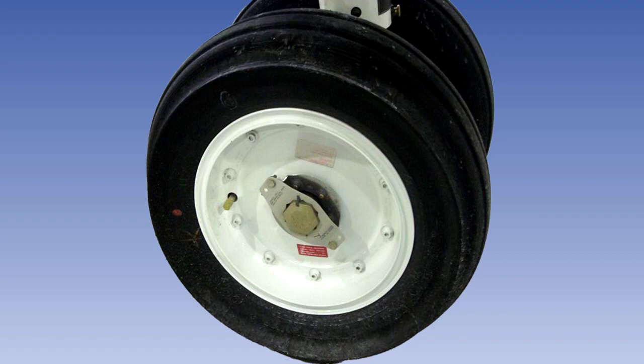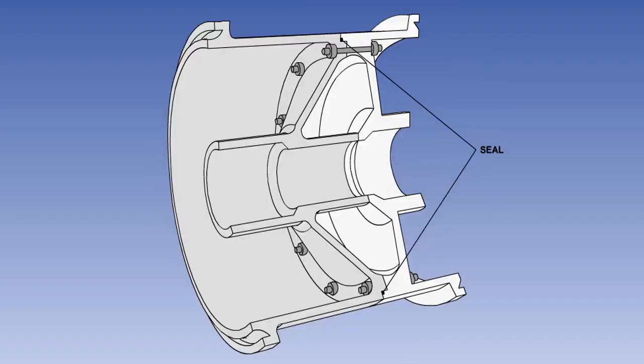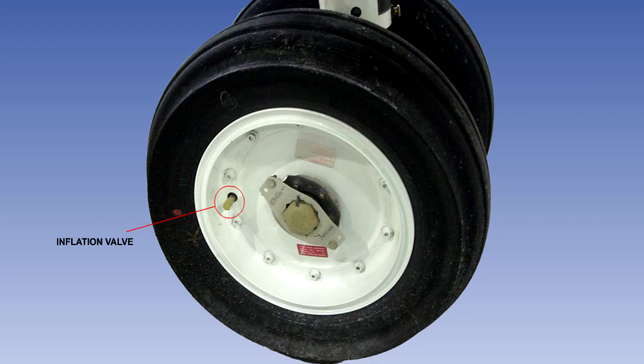Whichever alloy is used, after initial machining has been carried out, an anti-corrosive treatment is applied, and a final finish using cellulose or epoxy resin paint is applied to each wheel. Wheels for tubeless tyres are similar in construction to those for tyres fitted with inner tubes, but are ground to a finer finish and impregnated with Bakelite to seal the material. Seals are used between the parts of the wheel to prevent leakage. Unlike wheels for tyres fitted with tubes, the valve is fitted into the wheel itself and is thus not affected by creep.